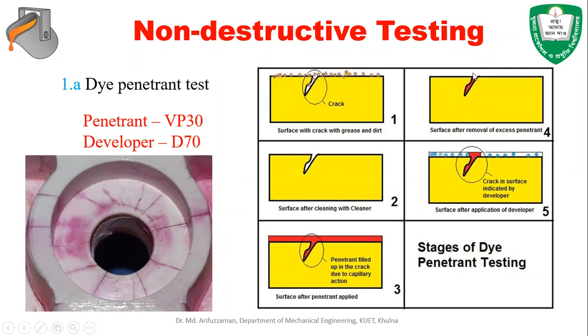Before taking out the penetrant, you won't be able to see anything. You will just see the plain surfaces. You will not be able to see the cracks. Because of using the developer, the penetrant has come out on the surface, and you'll be able to detect that change, don't you? That means it's not a direct change, but indirectly something is changing, and that is the probing medium, the penetrant. Because of using the developer, the penetrant is coming out. That is the change happening here.